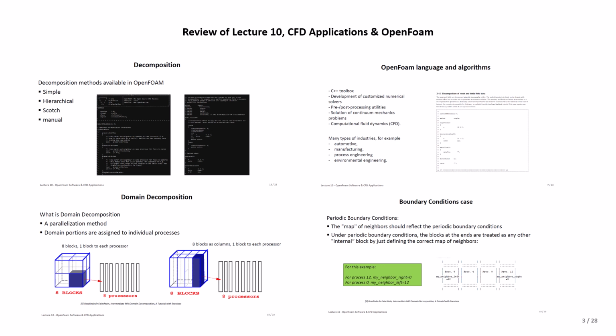It's open source software, and we can modify a new code for a new problem, and it's compatible with some visualization software like ParaView, and it has a great capability to run on parallel computing. We discussed that there are decomposition methods called simple, hierarchical, and Scotch, and what the advantages and disadvantages of them are.